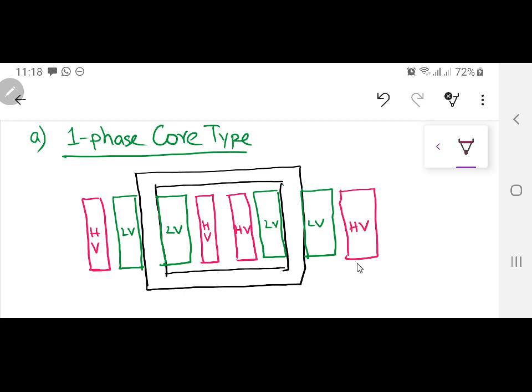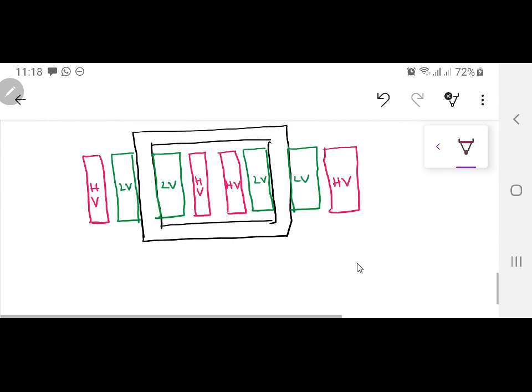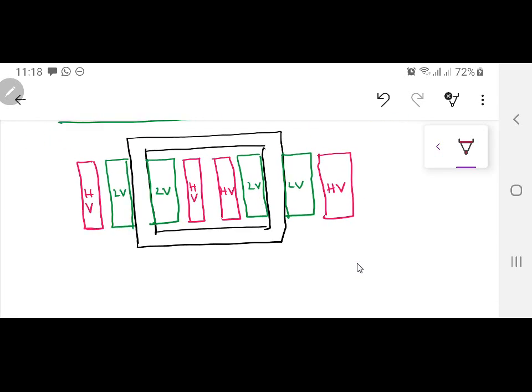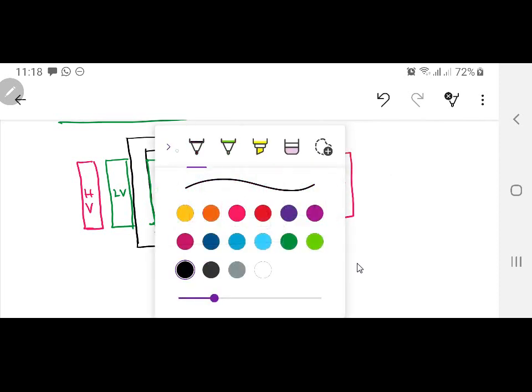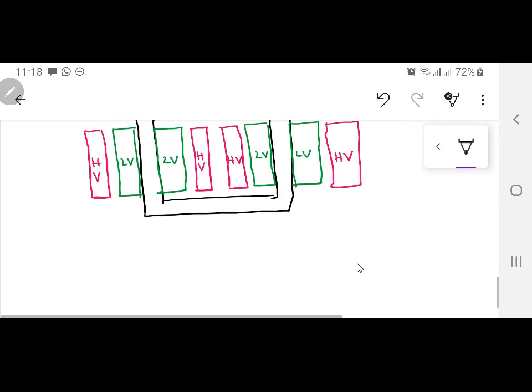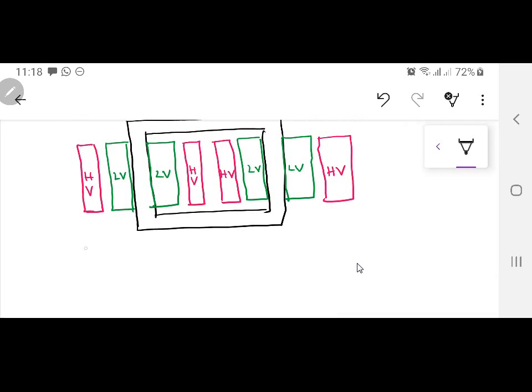So मैंने क्या किया है, I had n number of turns or n1 number of turns on the low voltage, half of the turns are here, half of the turns of low voltage are here. I can connect them electrically afterwards with the wires. So what I am doing over here, in this transformer, to increase the flux linkage, half of the windings of low voltage are here, half of there, same for the high voltage winding. Now before I proceed on further, some variables which I will be using a lot over here in this total derivation.